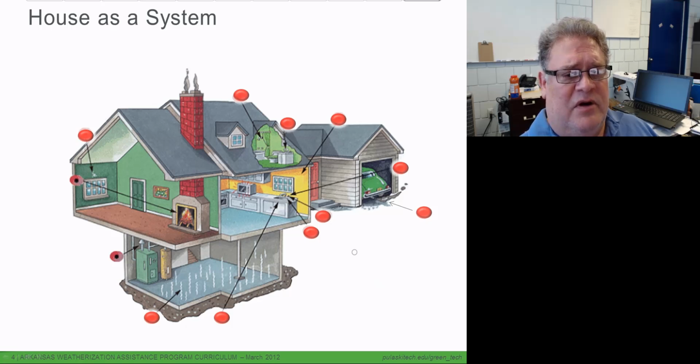Garages pose a special problem because we have a lot of pollutants in the garage, especially attached garages. Detached garages don't really cause a problem because we're not sharing the air from inside them. However, we have the potential with an attached garage to share that air. We can pull air in either through a fireplace or through natural draft, open combustion equipment. We can depressurize the house slightly and pull air in, but more likely it's going to be things like range exhaust fans,